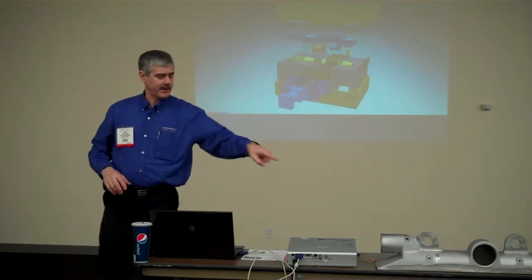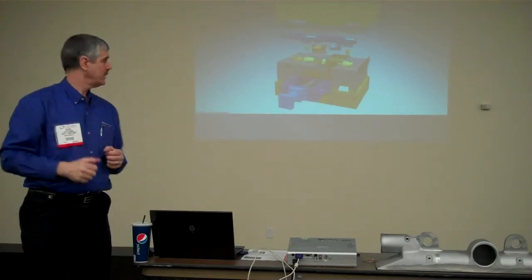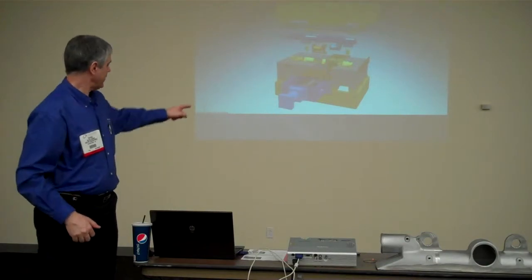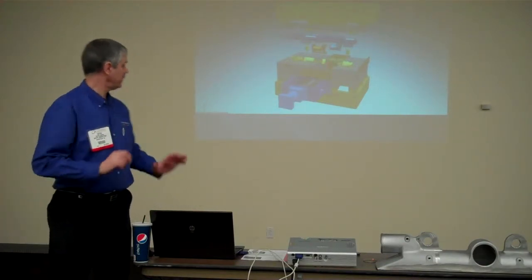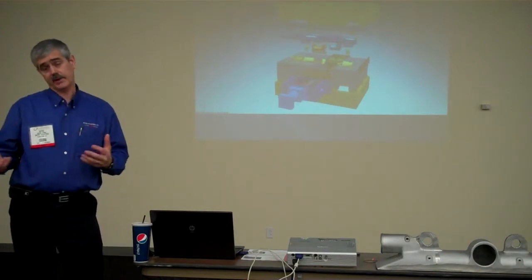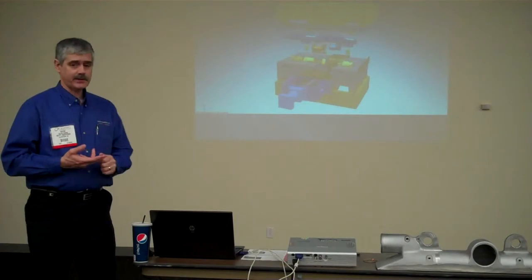It's much like this part I have here, where there's features that wouldn't draw in a typical mold opening. So we have sliding cores, and they're powered by hydraulics. That's the hydraulic cylinder there in the blue. So that's a typical mold. Maybe it's got a little bit more going on than the average mold, in the fact that it has steel cores, steel inserts, and a sand core.